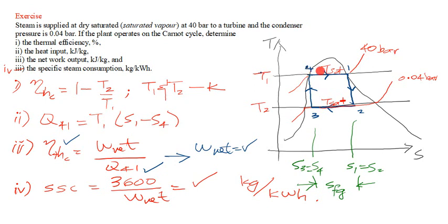And then 4-1 is in the boiler, which represents the reversible isothermal expansion. Due to that description of the processes which represent the Carnot cycle, for a steam Carnot cycle we can only do it within the saturation state.